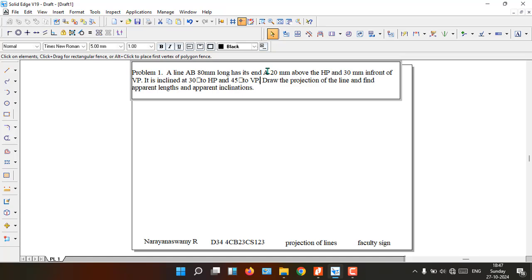But when you put a hand in to get that coin, you will come to know the actual length of it. That means the actual length of a line or the object or the distance is a different one, and the one which appears is a different one. The actual one is called the true length, and the one which appears is called the apparent length. If you take the same example with the scale, the length of the scale gets shortened, as if contracted, but the inclination will be a little more compared to the initial inclination.